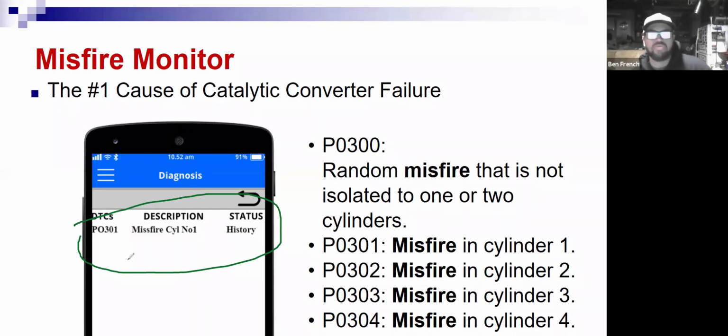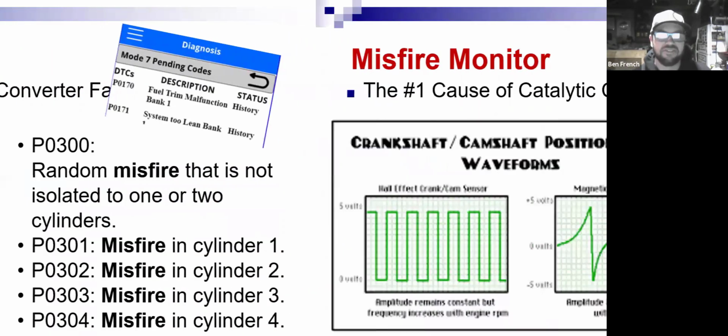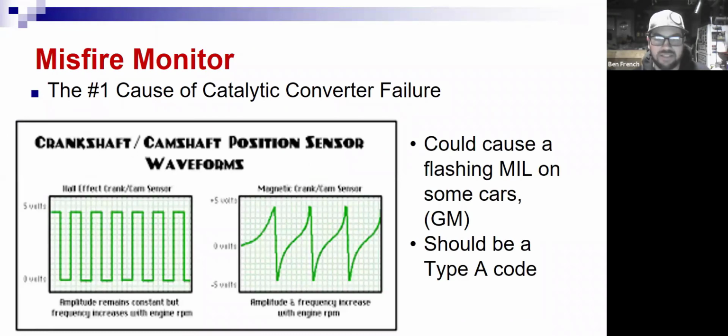If after a drive where I have a chance to run Misfire Monitor it's now setting misfires on cylinder 2, I can see that my misfire followed the spark plug. I know, hey, I got a defective spark plug. So a lot of times what techs will do is mix and match spark plugs, mix and match wires, mix and match ignition coils, especially on Fords, and they'll find their defective parts that way utilizing Misfire Monitor. And that's something that we couldn't do in OBD1. So we were looking at scope patterns and all that other type of stuff, doing a manual power balance.